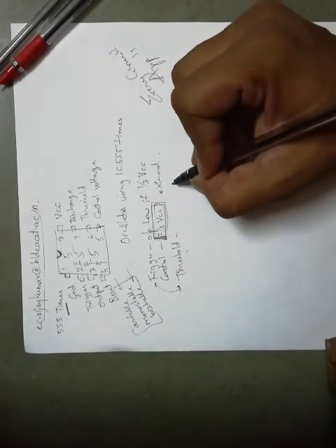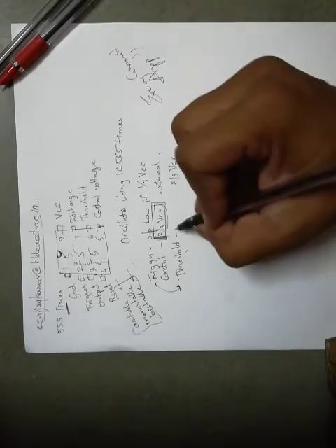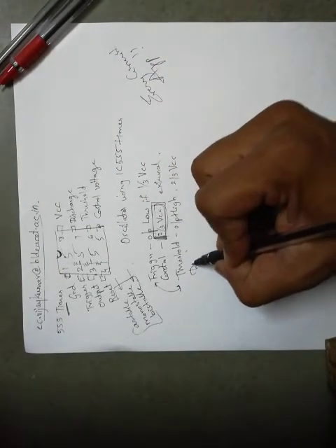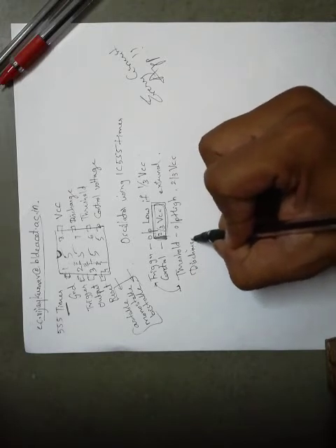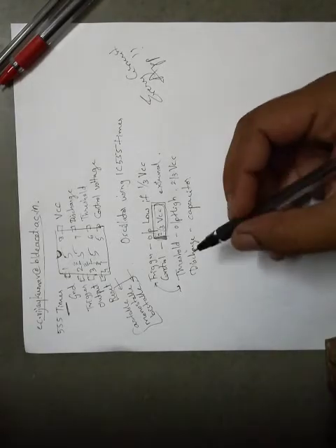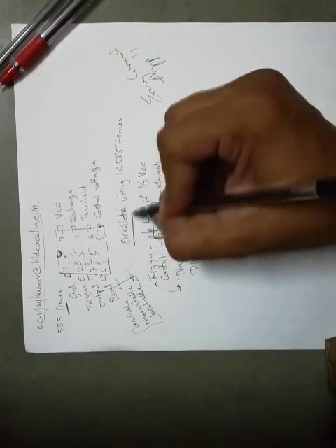In the threshold part, if 2/3 VCC is observed, output is driven high. Opposite work. The one left is discharge. Discharge pin is for voltage discharge through the capacitor, so that we can recreate the operation of timing pulses. So we'll start with our oscillator design.